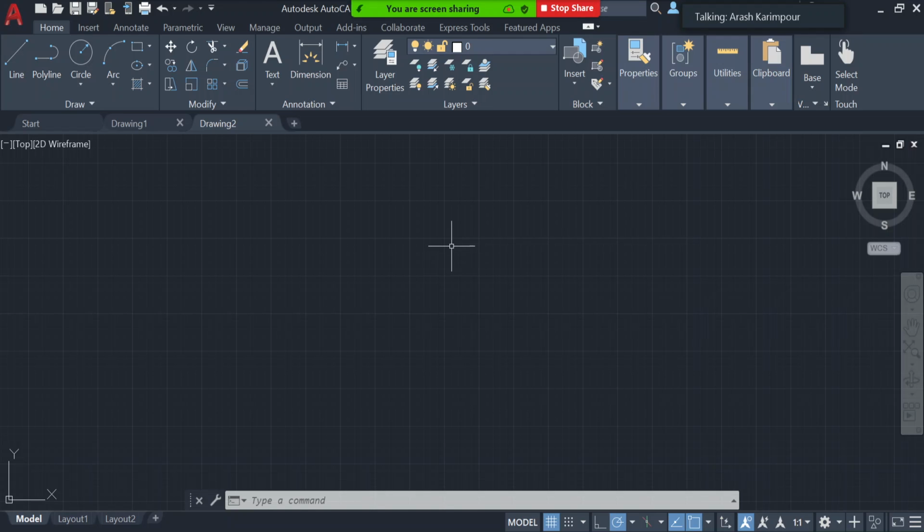So if I want to make any changes to, for example, the doors, I go directly to the layer that contains the doors and make whatever changes I want without changing anything or making something wrong in other layers. That's a very useful tool to work with.